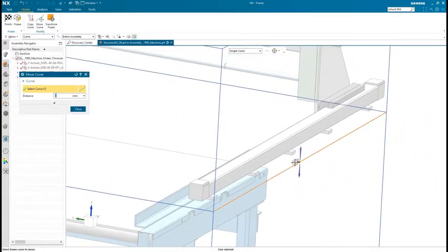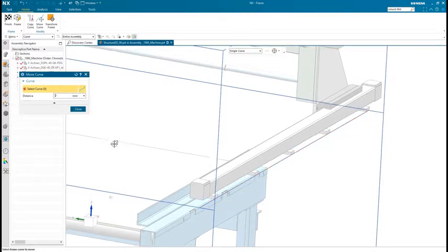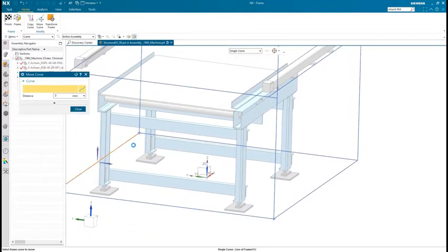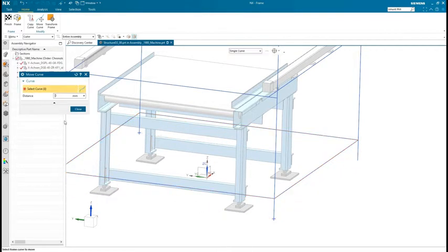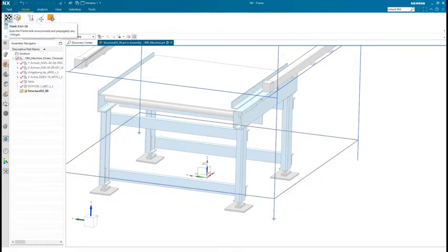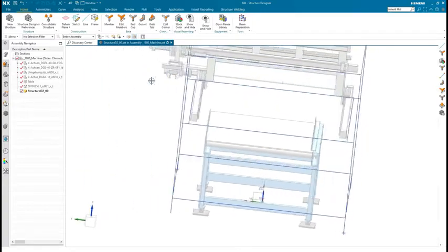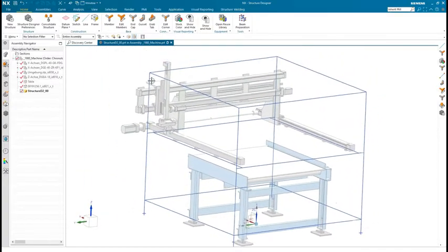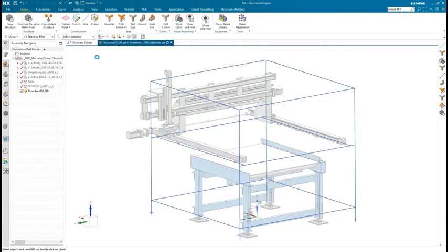We'll move these elements into position by using the mounting tabs as a guide. We'll repeat the process on the opposite side. Lastly, we'll add a footrest that will also stiffen the vertical legs. An element move will complete this process. During any move or copy, you can snap to existing geometry or enter a desired distance. You can also use sketch commands to create the cage.